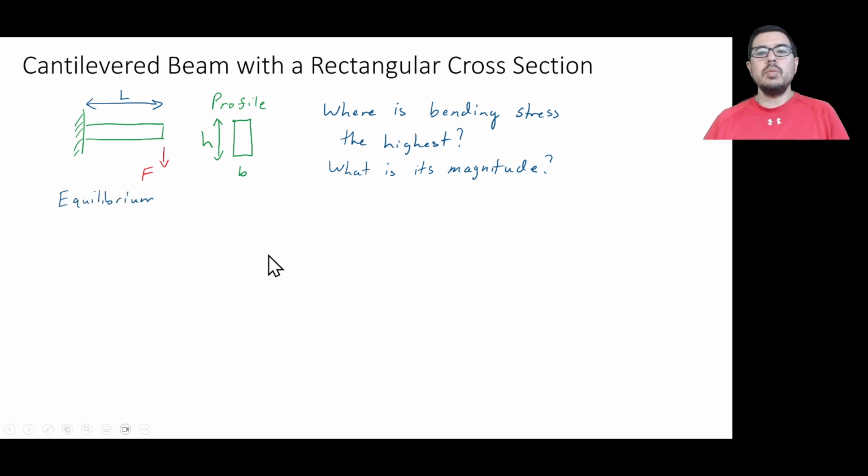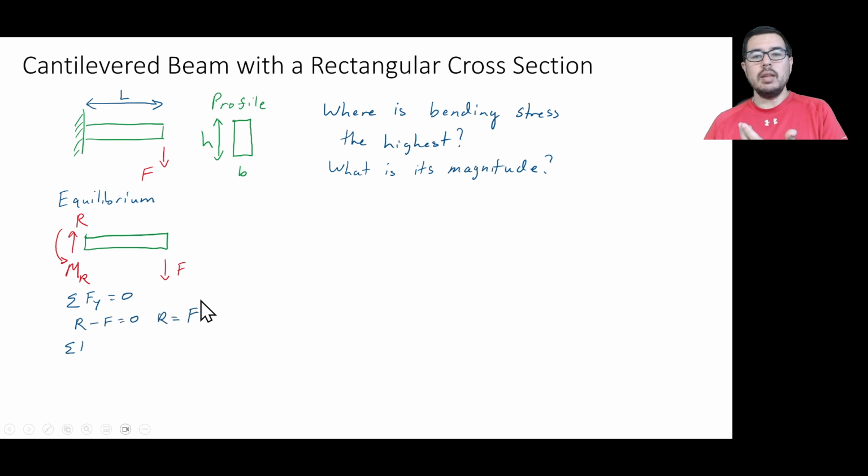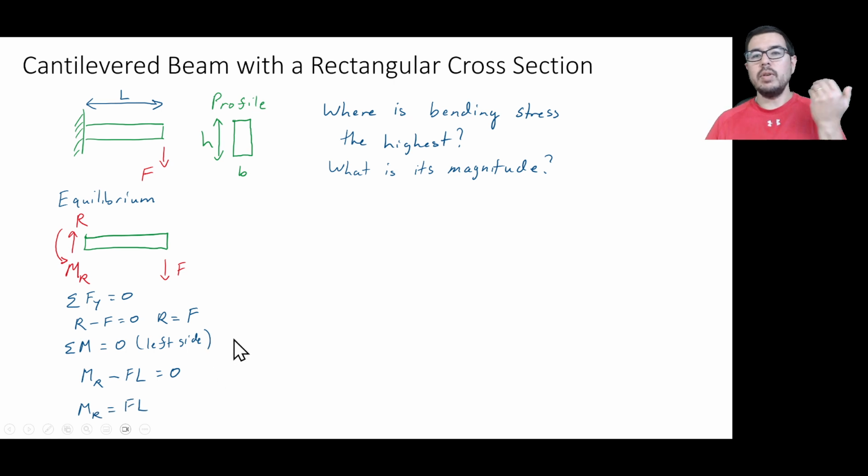Once again, a good place to start with this problem, and you've now seen me goof a little bit if you've been in class, is the creation of shear force and bending moment diagrams for this system. We start by doing external equilibrium, and we calculate. I'll go through this quickly because we've done this multiple times. And we have our reaction moment, we have our reaction force R.